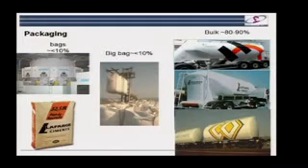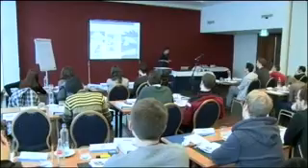I think everybody has this kind of idea of a bag of cement, but today, in Europe especially, very little cement is actually sold in bags, less than 10%. Most of it, by far and away, goes by bulk, either by road transport or by trains. And again, you've got to have in mind that you've got to make cement quite locally, because it's really only practical to transport it by road a distance of about 100 kilometers. Rail is more efficient. You can transport it typically 300 kilometers.